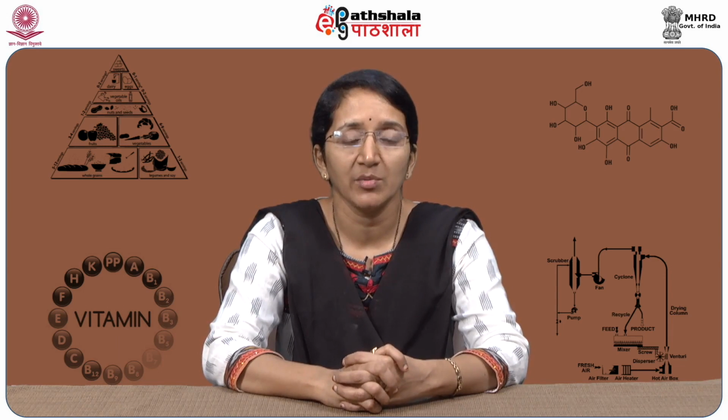Today, if a canned food is being sterilized, each food particle must receive the heat treatment. If we want to know about canned food and how it is being sterilized, we have to assume that each food particle must have received the heat treatment of 121 degrees centigrade for at least 15 minutes.